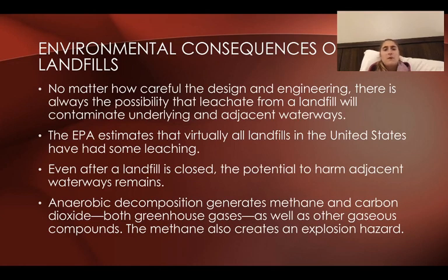Okay, so what are the environmental consequences of landfills? Of course, no matter how much engineering you do on designing a landfill, there's always the possibility that the leachate is going to contaminate something adjacent, waterways, soil, things like that. It'll be impossible to collect all of that, so you'll always have some. It's always going to be producing methane gas, just like the one next to us, and methane is a greenhouse gas, so you always run the risk of emitting greenhouse gases if you're not properly maintaining those methane emissions.